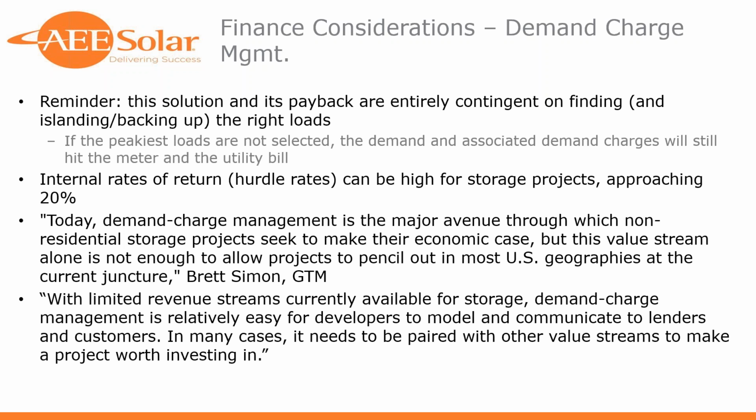And what I mean by that, if you're not selecting those peak loads and you're not addressing them, those loads are still going to hit the meter. You're still going to be driving a peak demand charge, and you're going to have to, hopefully best case, go out and rewire some things. Worst case is you size the system improperly, and you're going to have to go back and hopefully secure a change order and redesign the system.